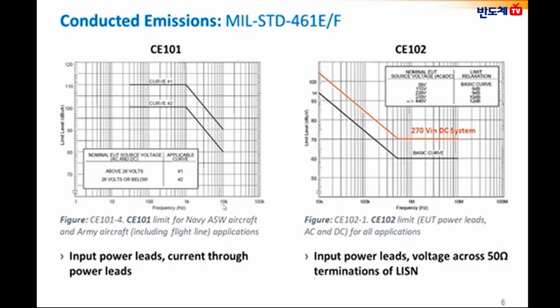In this slide, I would like to discuss the EMC standard requirements applicability in defense applications. Some of the defense applications require more conducted susceptibility or conducted emissions or radiated emissions or radiated susceptibility tests, whereas in general, the defense applications are required to meet the CE101, CE102, CS101, CS114, CS115, CS116, which are highlighted in the red text.